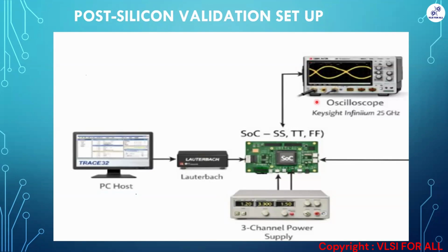Prodigy is a PC-based logic analyzer to analyze the waveform, and to capture and display the digital signal. We'll use Prodigy as master and the DUT as slave, and as well we can use the SoC as master and Prodigy as slave. That is basically to analyze the functionality. To check the correctness of the logic of any IP, we'll use logic analyzers.